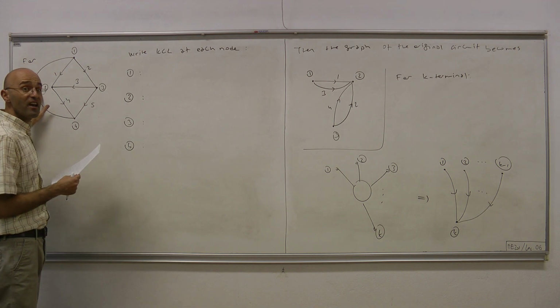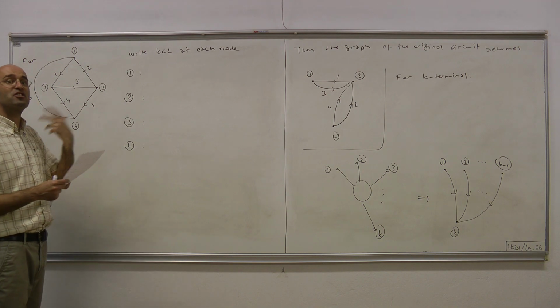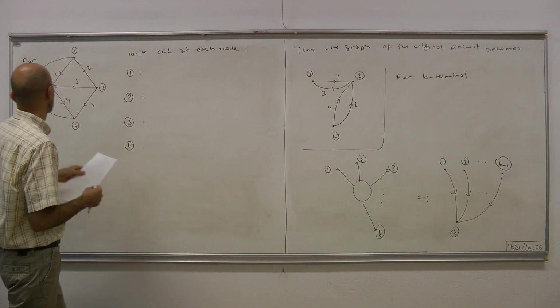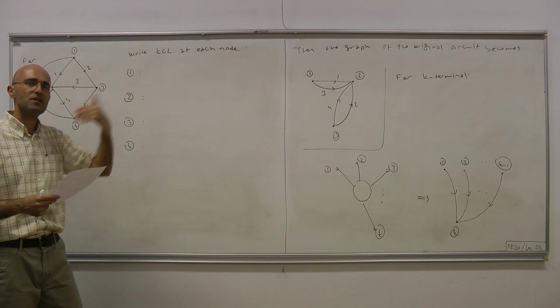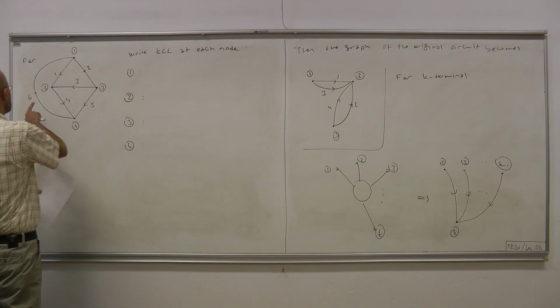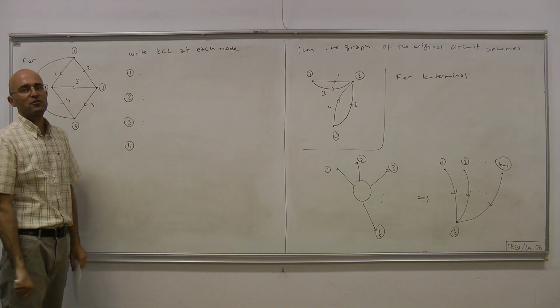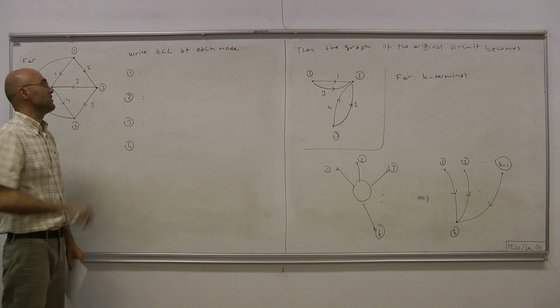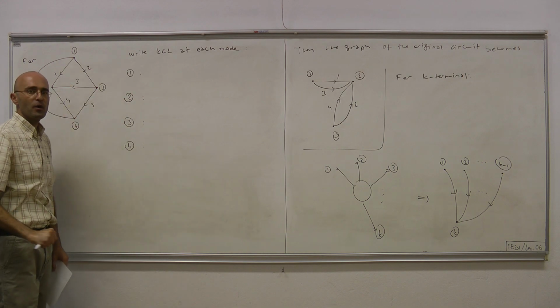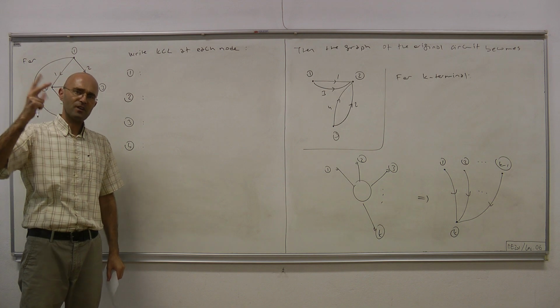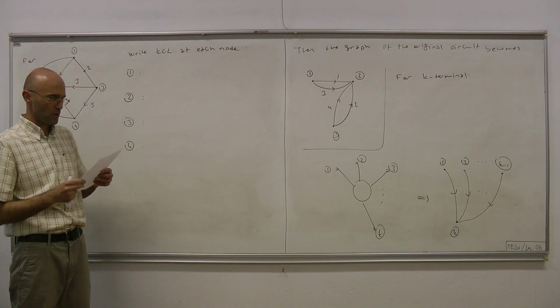But this 6th current, I6, is incoming. How can we treat it as an outgoing current? All we have to do is reverse in our heads the direction. Now, if I6 is incoming, then minus I6 we can treat as the outgoing current. And in that case, since all the currents are outgoing and there's no incoming current, then that sum must equal 0.